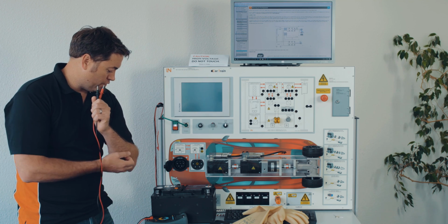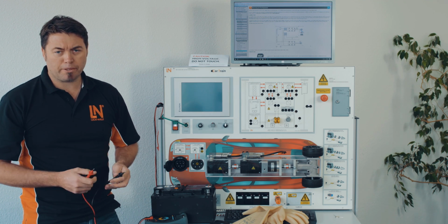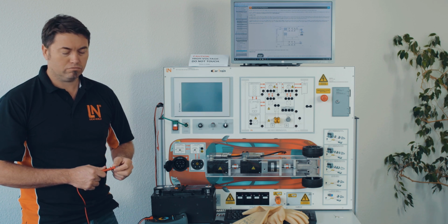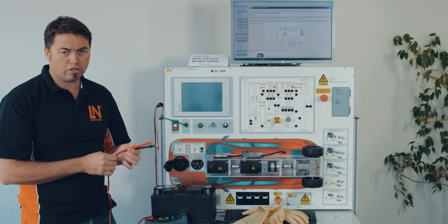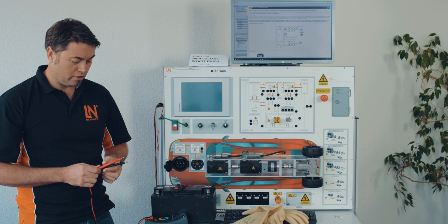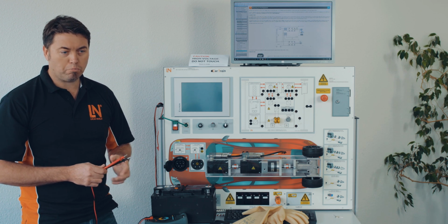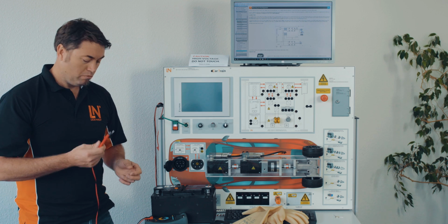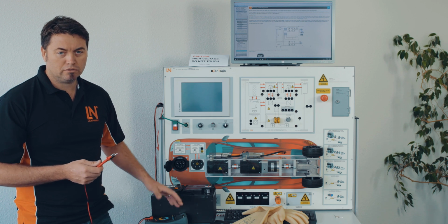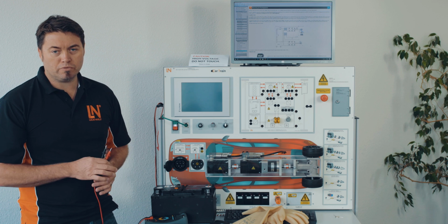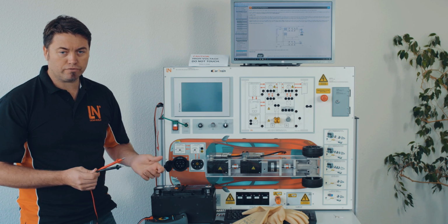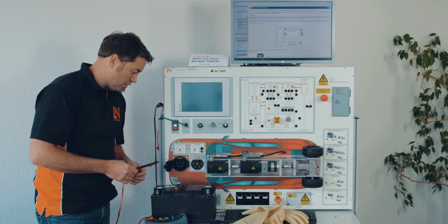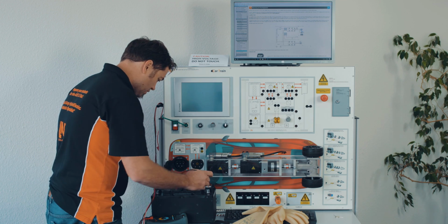Because if we've got a faulty multimeter, the fuse is blown or something, and it just says 0 volts, and we go along and check the high voltage connection, and it says 0 volts, but it might actually have 200 volts on a battery voltage, due to a faulty multimeter we've just got a false negative.